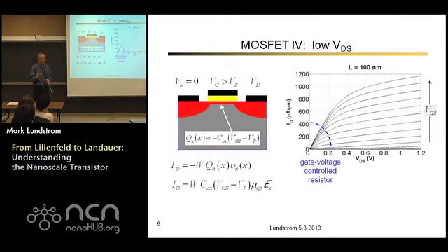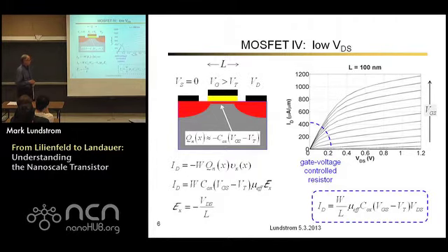It's just like a resistor. The velocity is mobility times electric field. The electric field is just pointing from the drain to the source, so it's negative, and it's just the voltage across the 2 terminals divided by the length of the channel. Plug that all in, and we get this classic textbook expression for the IV characteristic of a MOSFET in the linear regime. All right. Easy to do.